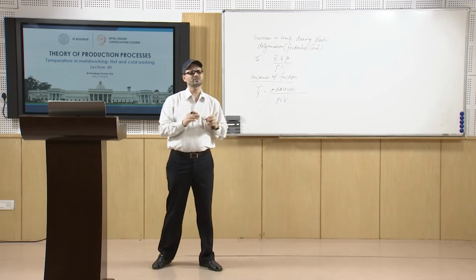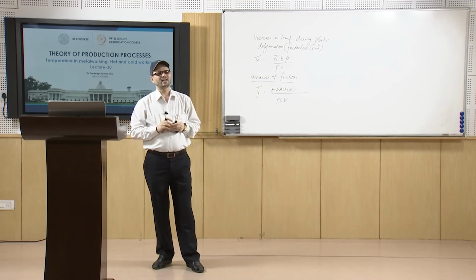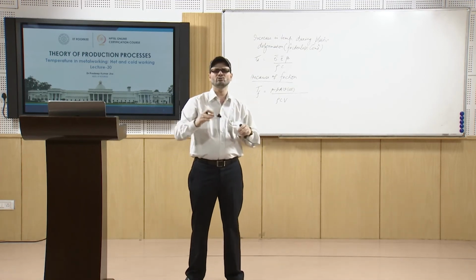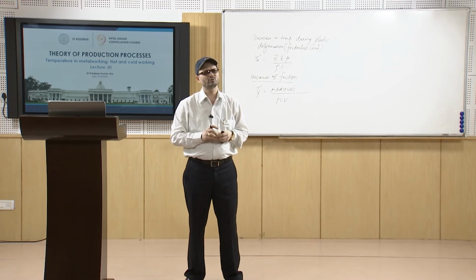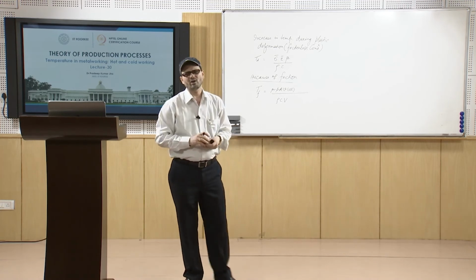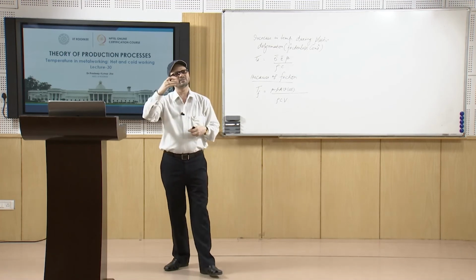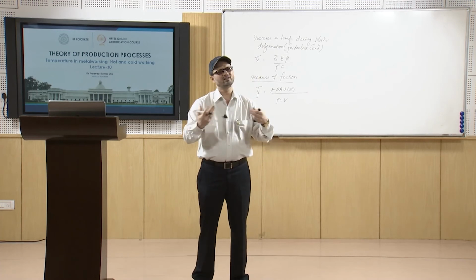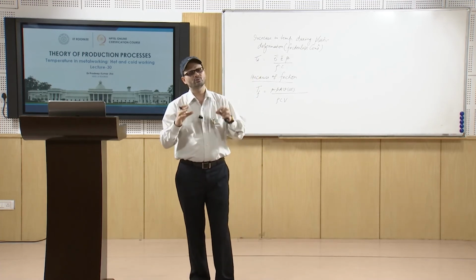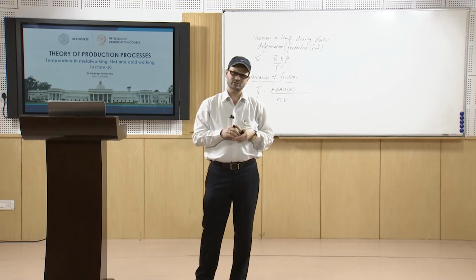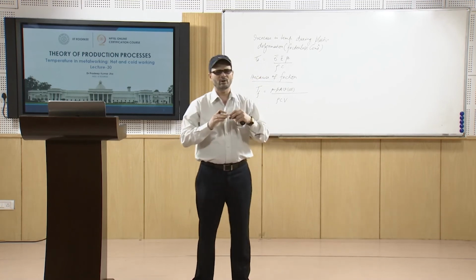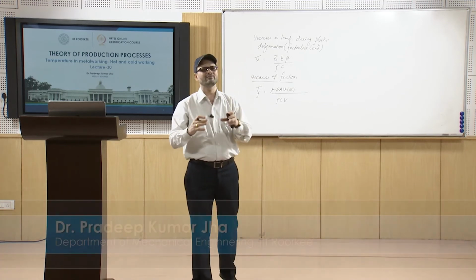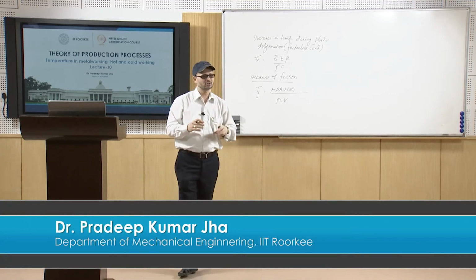Another important consideration to be kept in mind is that these are not operations in which you get the final shape in only one go. So, you have many intermediate passes. Intermediate passes are normally done at a higher temperature. When you work at higher temperature, certainly the flow stress requirement is less. So, you require less force to do the deformation, but if you linger there, the chances of grain growth will be more. So, you will have coarse grained structures, which is not desirable.